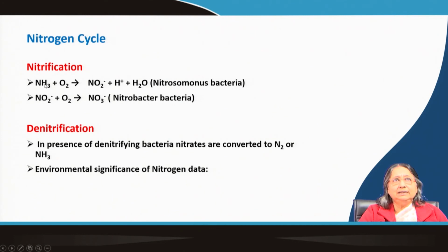So ammonia is oxidized by the oxygen there and it is called the NBOD. Up to 5 days it is CBOD. So it is the conversion of carbon that is present in the organic molecules to carbon dioxide. After that, the nitrogen containing compounds also take part in this type of reactions to form the nitrites and nitrates, okay.